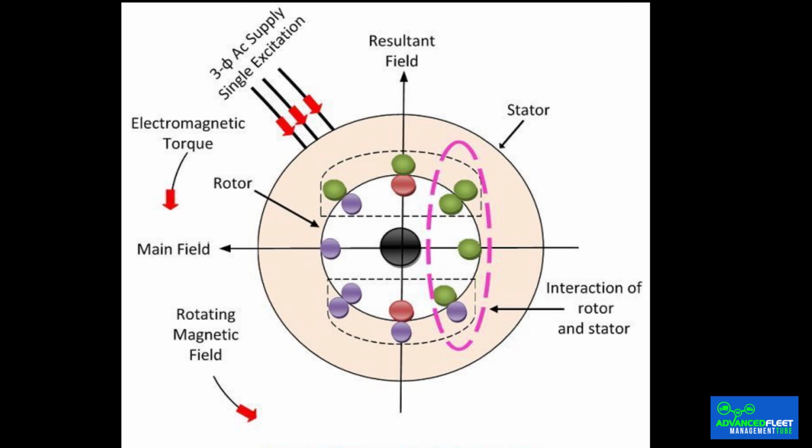The asynchronous motor. The asynchronous motor is governed by Faraday's principle of mutual induction. When three-phase alternating current is applied to the inductor coils, a rotating magnetic field is generated, called a rotating field, whose frequency is equivalent to that of the alternating current supplying the motor. This field, when rotating around the rotor at rest, induces electrical voltages that generate currents in it. These, in turn, generate a magnetic field that replicates the motion of the stator field, thus producing a torque that rotates the rotor by the principle of mutual induction.